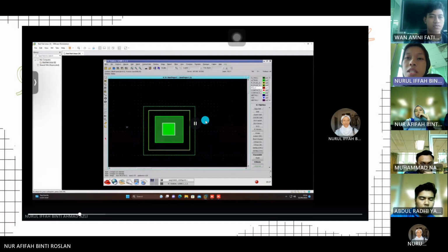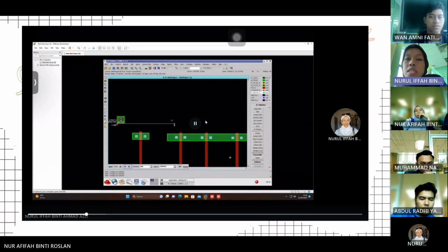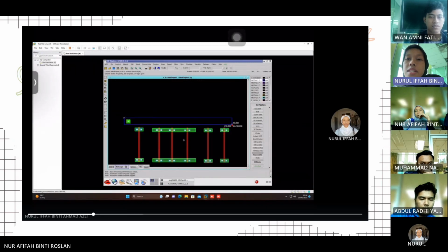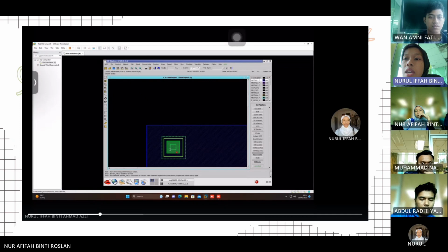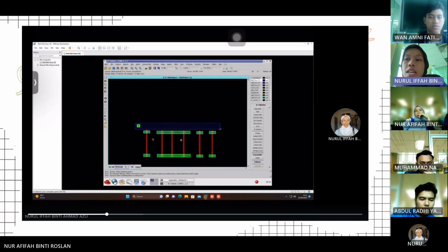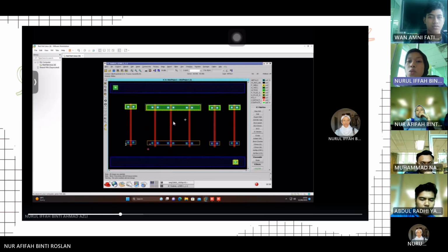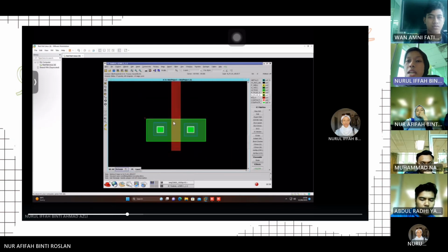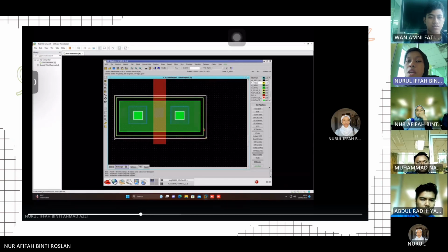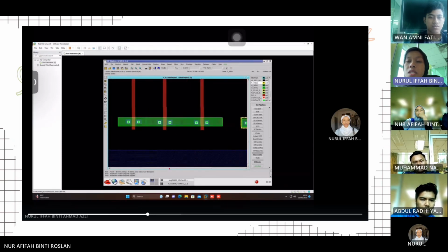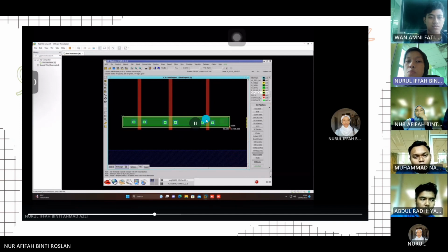I am adjusting the position to make it center, and then put metal above the layer that I made just now, and the VDD is done. Next, the poly. There are 7 poly in this design. Also, we insert the active layer N+ and P well for NMOS, which is the pull down network. For PMOS, I am inserting P+ and N well, which is the pull up network.